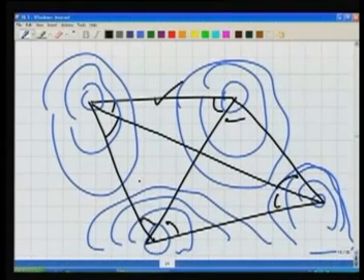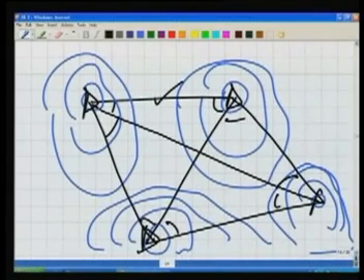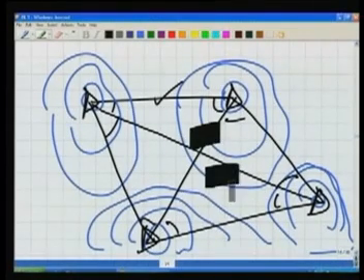Now I have got the control established for this area, and using this control, these triangulation stations, later on I can make a map of this entire area. Everywhere here I can make the map. So this braced quadrilateral is a very useful figure.